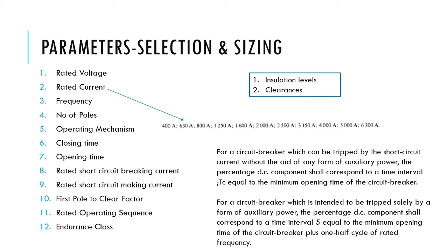So why do I require this? Otherwise I am losing some load. If one of the phases does not exist in the system, it results in unbalanced loads. We already know this, but why am I opting for it? Because in transmission lines, generally 80 to 90% of faults are transient or temporary faults. Only 10% of faults are permanent faults. Remaining all are transient faults.